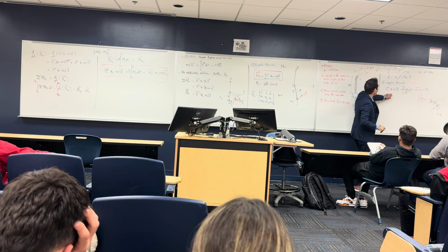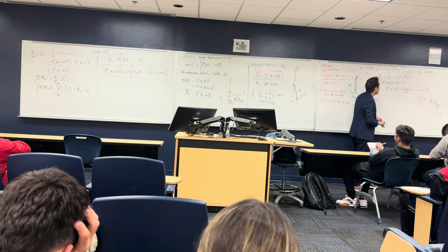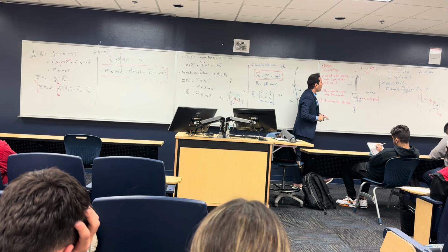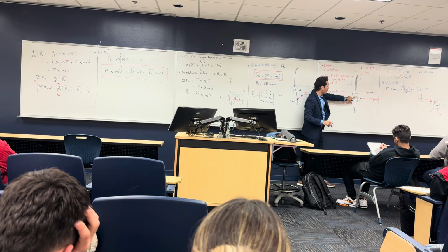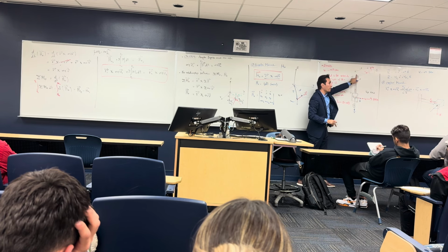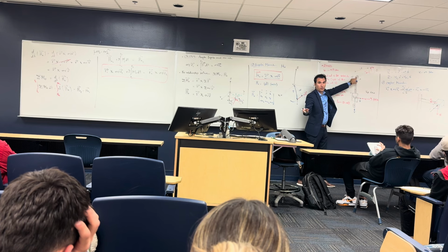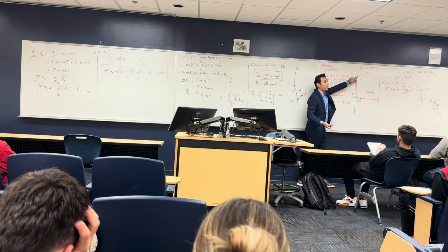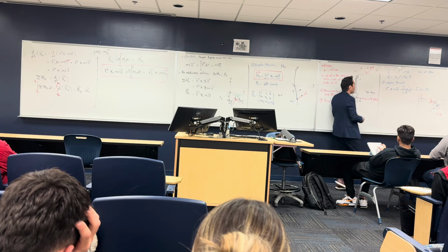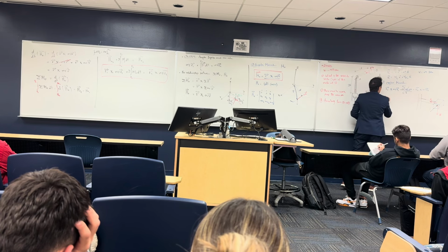Okay, so we will be left with R1 multiplied by V1. You guys tell me, what is the value of R1? The position, the R. What do you guys know what is R? It's the position from the body to the point that I'm getting the moment about. 2 feet. So 2. Is it positive or negative? It's always positive. Oh, positive. Because it's going this way. It's going to be 0 if it's in the other direction. So the R vector is 2. Alright, what is the direction of this 2?